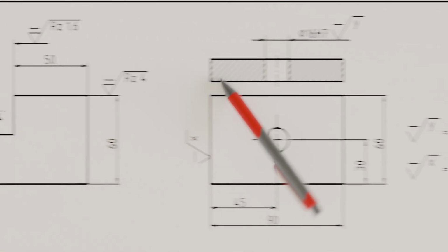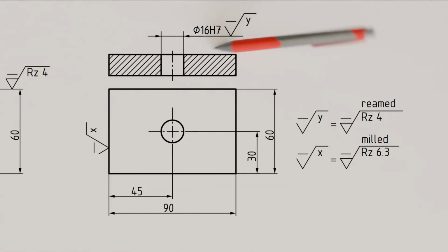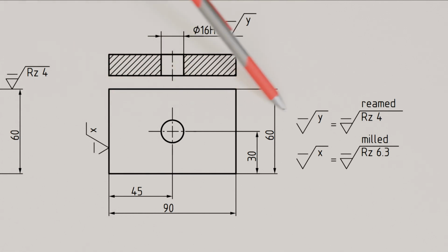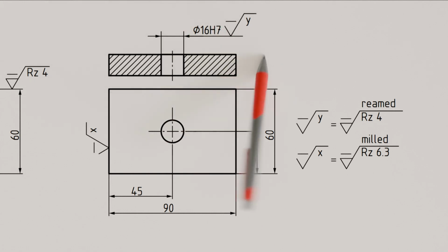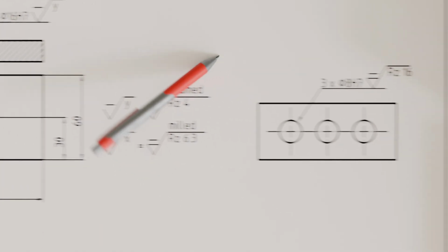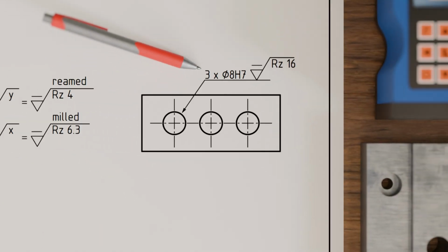For complex surface specifications, a simplified notation is permitted. The detailed explanation of the simplification must be located either near the component or near the title block of the drawing. If there are multiple views of a geometry, the surface symbol is always placed in the view where the dimension is also shown. If a geometry with a required surface property appears multiple times on a component, for example in holes, the surface symbol is only applied once in conjunction with the dimensioning of one geometry.